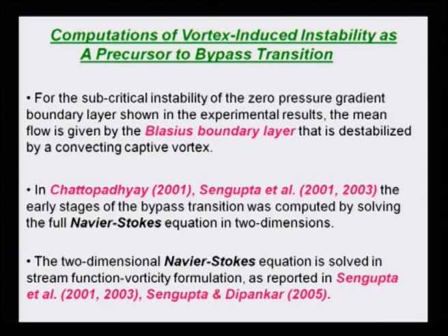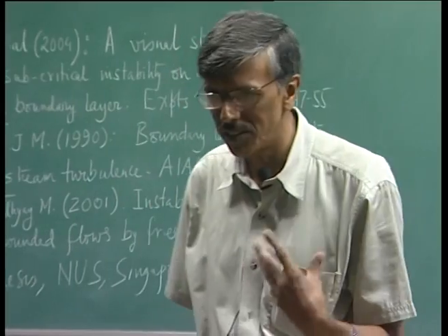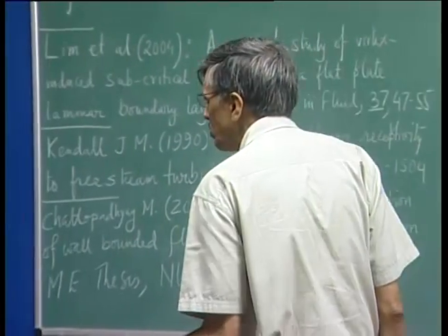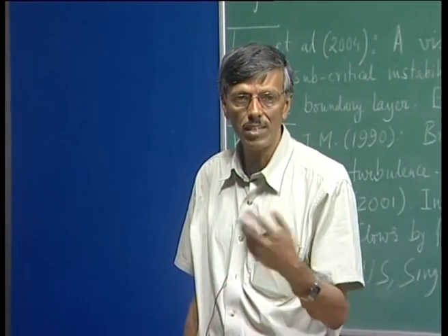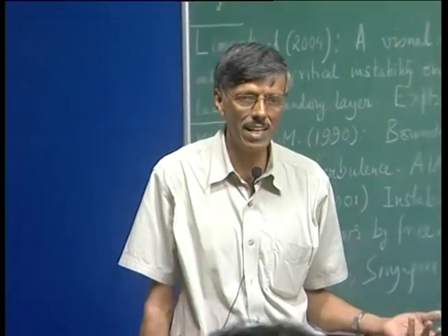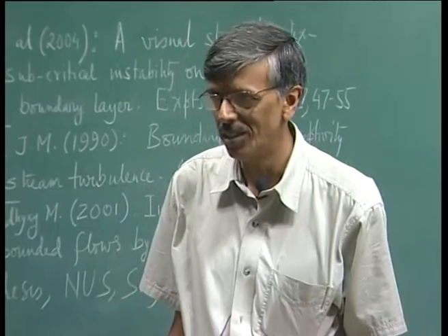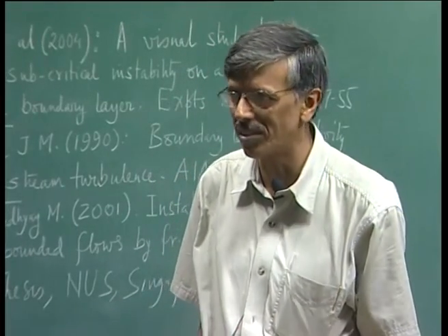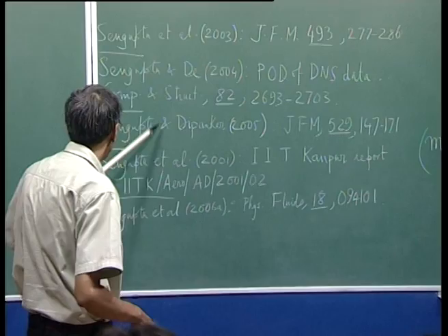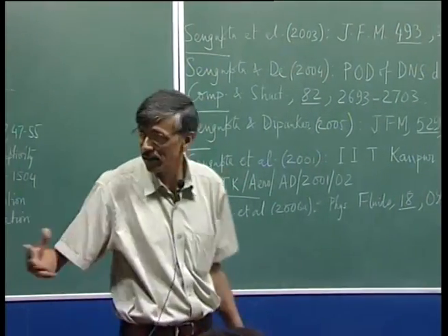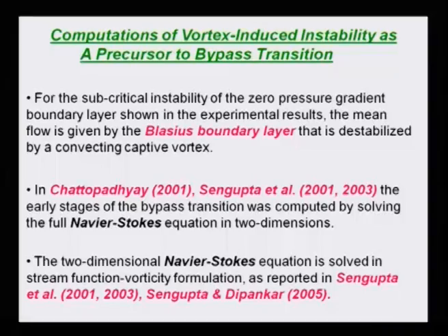Okay. And what you do is take up the Navier-Stokes equation in stream function vorticity formulation, and this you do basically for accuracy's sake, because the existence of psi, the stream function, would ensure mass conservation in a numerical sense, and basically fluid mechanics is all about vorticity dynamics. So, there is nothing better than working with the vorticity itself. So, this formulation is always recommended. These are the references that you can see, and in this we have defined all the methodologies that are written there.